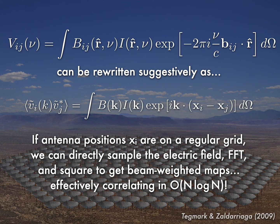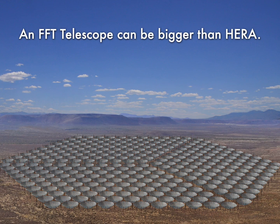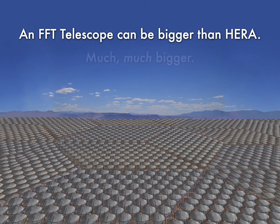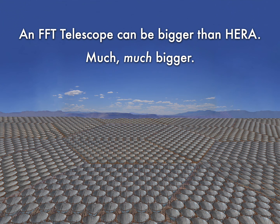All of a sudden, the correlator is no longer the most expensive part, because n log n grows so much slower than n squared in terms of cost. So this is what we mean by an FFT telescope, a telescope that uses this kind of technique to achieve very large collecting areas. Now, I don't think it's going to look like HERA, but an FFT telescope can be much, much bigger than HERA.